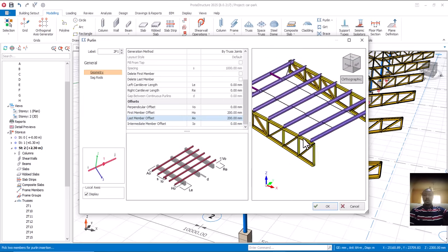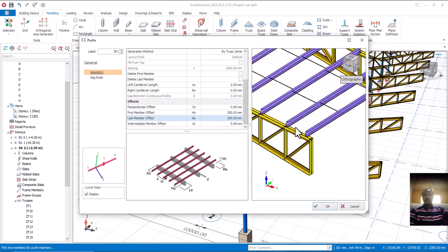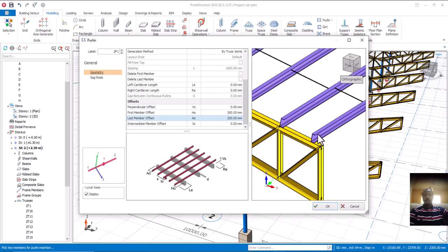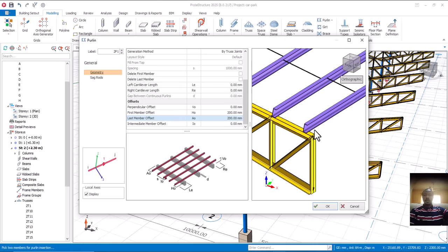And don't forget that your zinc definitely will project and is expected to cover this. And if from here to this place is 200 already, don't forget that your zinc will not only stop at this point. Is that okay? It is still expected that your zinc should extend out in order to cover these particular trusses, isn't it? So if you now look at this 200 plus that one that will also extend out, you now discover we are having almost like a, let's say, 250 or 275 or whatever.